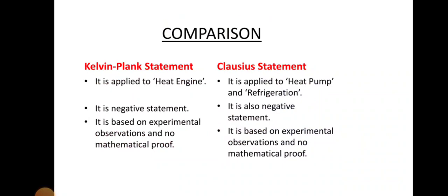What is the meaning of heat pump? A heat pump is a device that transfers heat energy from a source of heat to what is called a heat sink. A heat pump moves thermal energy in the opposite direction of spontaneous heat transfer by absorbing heat from a cold space and releasing it to a warm one. A heat pump uses a small amount of external power to accomplish the work of transferring the energy from the heat source to the heat sink.